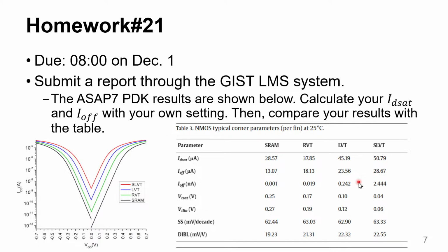I think that the possible reason is EOT, equivalent oxide thickness. We have used exactly 1.0 nanometer for EOT, and it can have different numbers, so that can be a possible reason for the reduced on current at a similar level of off current. But anyway, since we do not alter the material parameters, we can just live with the present model.